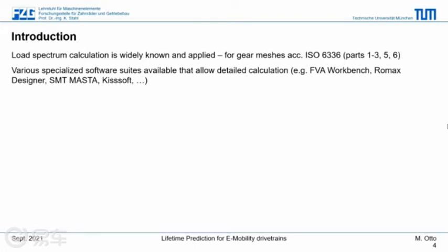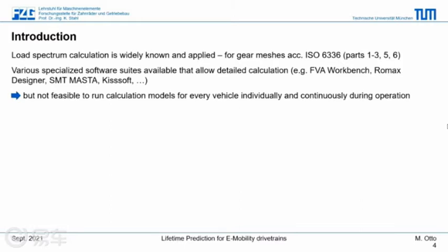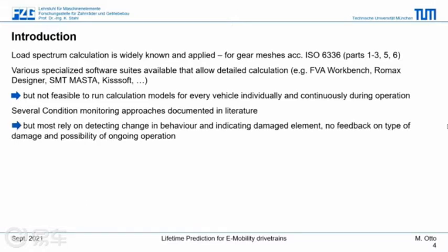Load capacity calculation is widely known and applied for gear meshes, according to the international standard ISO 6336 and its parts, and various specialized software suites are available that allow detailed calculation, for example FEA Workbench, Romax Designer, SMT MASTA, GEARsoft, and a lot more. But it is not feasible to run calculation models for every vehicle individually and continuously during operation due to calculation time and effort. Several condition monitoring approaches, on the other hand, are documented in the literature.